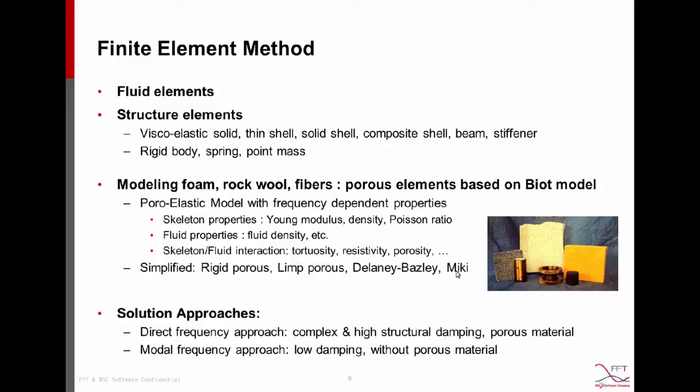And about the solution approaches, in Actran we have both the direct frequency response approach and the modal frequency response approach. The direct frequency approach is very suitable for the case where we have a complex and high value of structure damping and porous material. While the modal frequency approach is interesting because it often reduces the computational cost, but it's only suitable for low damping structures and without any porous material included.